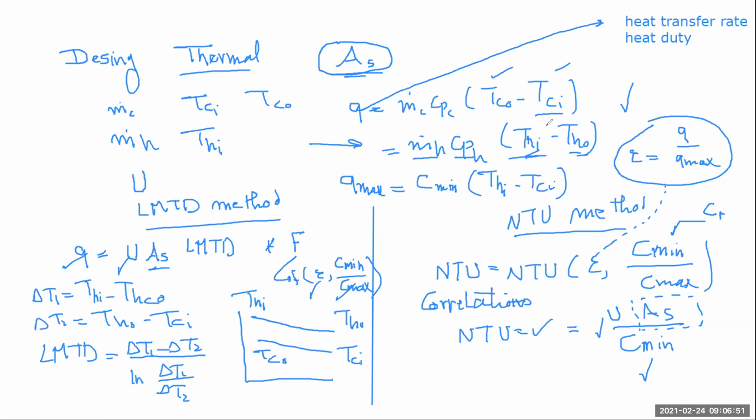Titanium has problems. Number one, it's very expensive. Number two, its thermal conductivity is less than that for aluminum. So they used to use thin tubes of titanium, and they use it only for the first few stages, and then the rest of the stages can be made of copper nickel. So the point here is it's a trade-off between the cost that you have to pay and the function that you need to achieve. I hope I did answer your question.